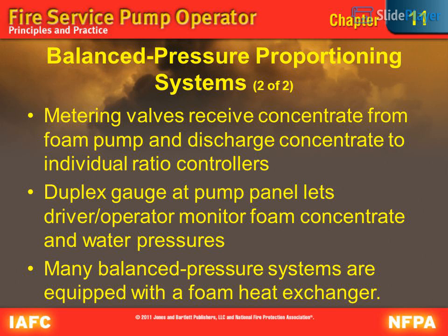Metering valves receive concentrate from foam pump and discharge concentrate to individual ratio controllers. Duplex gauge at pump panel lets driver/operator monitor foam concentrate and water pressures. Many balanced pressure systems are equipped with a foam heat exchanger.